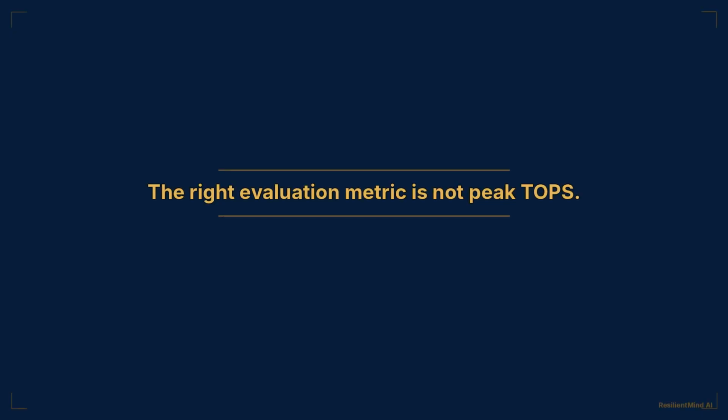The right question for any edge AI platform evaluation is not how fast it runs. It is, what is the power normalized throughput at my operational thermal ceiling, and what model classes execute reliably within it? The architecture answers that question in silicon. Your job is to read the answer before you commit the integration budget.